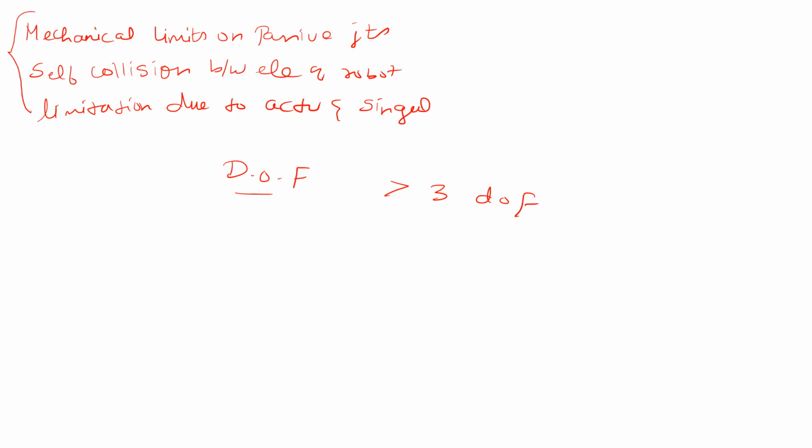For example, the workspace of a 6 DOF serial robot with a concurrent axis wrist may be represented by the 3D volume that may be reached by the center of the wrist. This illustrates the translations, and by the surface that may be reached by the extremity of the end effector, which illustrates the 2 degrees of freedom in rotation.